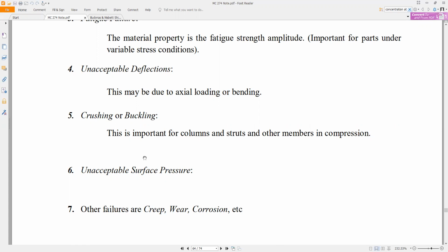And I gave an example of testing the crushing strength of a rock, for instance. You may go to the geology lab to see how it's done. When we are compressing it, you see that because the rock material is very brittle, it will crash. You will not see it bending or buckling. It will just crash. That is the failure of that rock material. When the crushing force exerted on it introduces compressive stresses that are more than what the rock will handle, it simply crashes, and that causes it to fail.